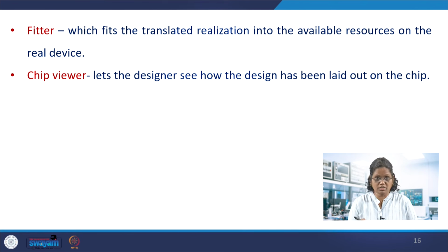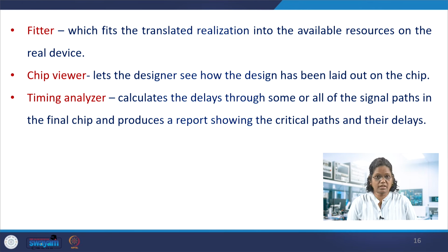The timing analyzer is also part of it, and it is very important when we try to implement the design in the FPGA. This timing analyzer takes all the paths from input to output and finds out the delays in each path, and also finds the critical paths, the maximum path, what the delay in the path is, and whether it is matching with the clock or not. With the given clock, can these delays be handled or not? So this timing analyzer looks at all the signal paths and figures out what delays are involved in the design.